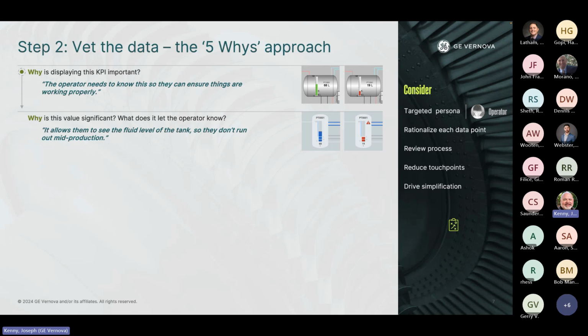Okay, so you can see a scenario here where if the fluid's lower, I've actually changed it more to a high-performance HMI graphic where I actually have an alert symbol next to it in case you have someone who's colorblind. For instance, the first scenario I showed you wouldn't work for someone like that because they might not be able to see the difference between the blue and the red.